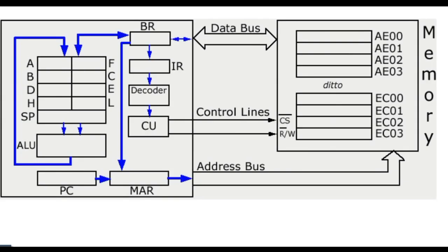This is a simplified schematic diagram of a microprocessor system, and we're going to be using this to describe the fetch, decode, execute cycle for the machine code instruction responsible for incrementing the contents of register A. We have already seen that the hexadecimal number 3C represents the instruction that will be responsible for incrementing the contents of register A. Now that has to be put in memory.